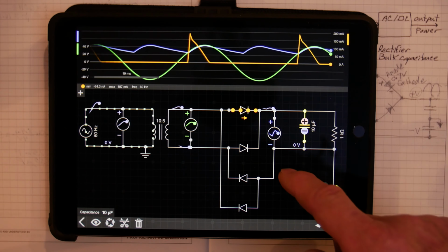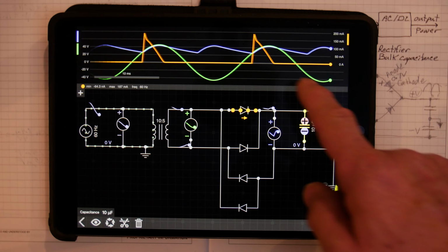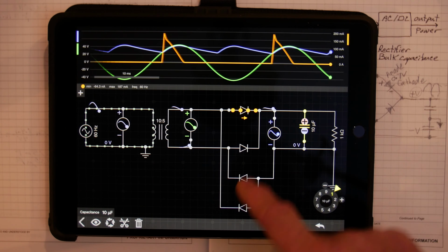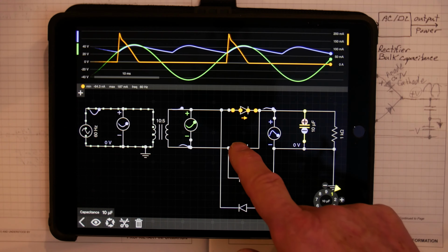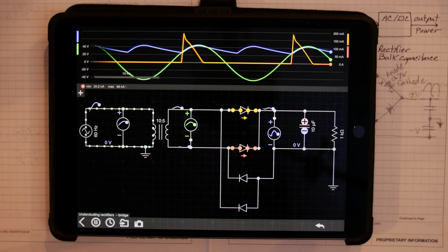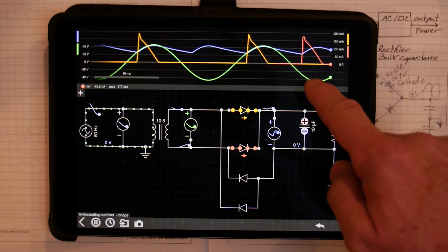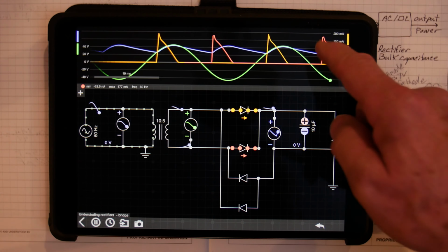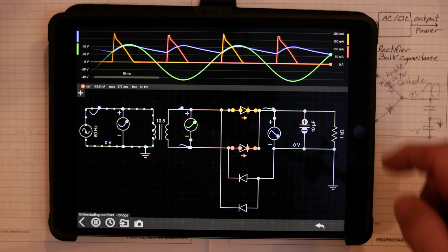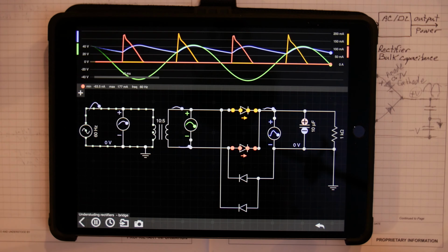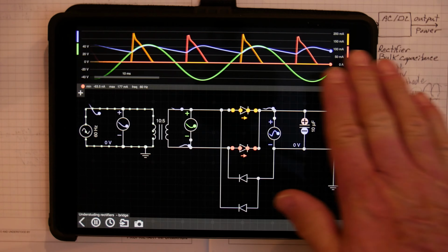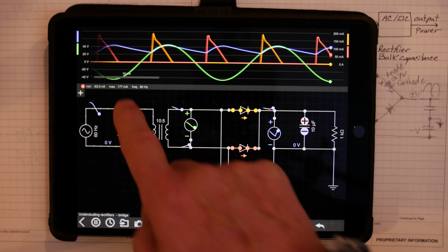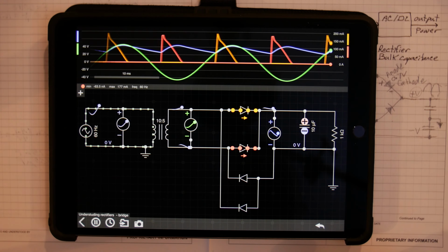So we're getting a charge cycle here, obviously, because you can see the voltage gets bumped up. It's from the other diode. We can look at that too. So now the red one turns on, then the orange. So every cycle we get a pulse, and it's 187. Well, we had to kind of charge up the capacitor, and so now they're all charged up. It's about 177 milliamps.